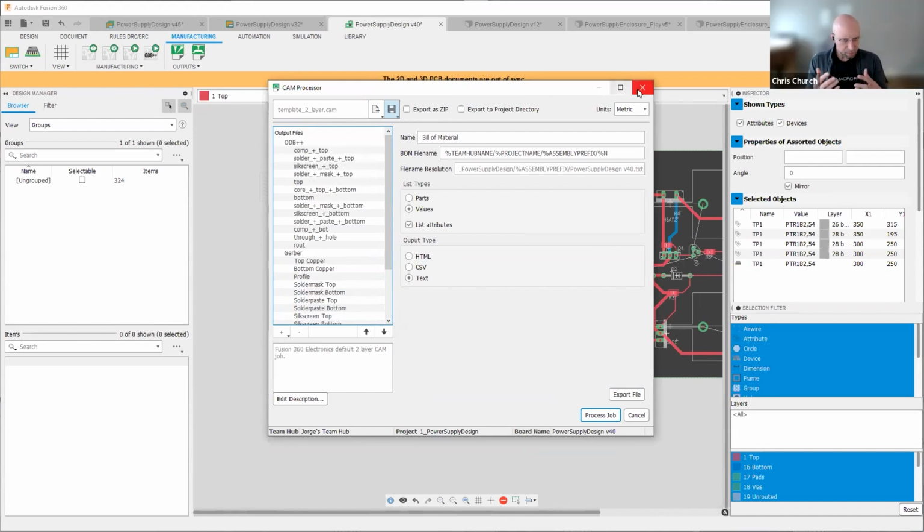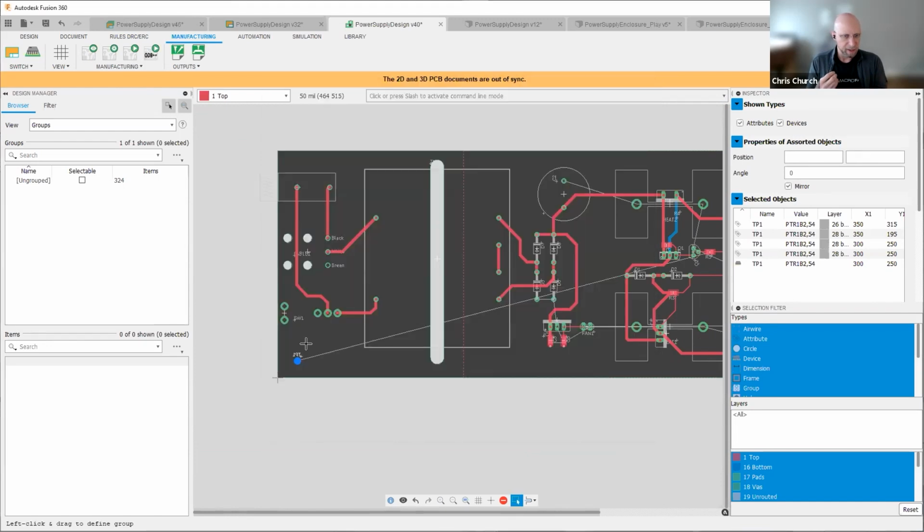Yeah, so Gerbers are perfectly possible, and we get a lot of designs that are Gerbers and bill of materials, pick and place files. That does require a little bit more work on the user's part because sometimes these things don't line up perfectly with each other depending on how you export them, and we lose a little bit of knowledge about the design itself. What we have are your traditional manufacturing outputs. So we have two options there. We can take the Eagle file directly, which is a very rich information source. We can process that. But we do have a lot of customers who are concerned about their IP. They don't want to send their entire design database to us.